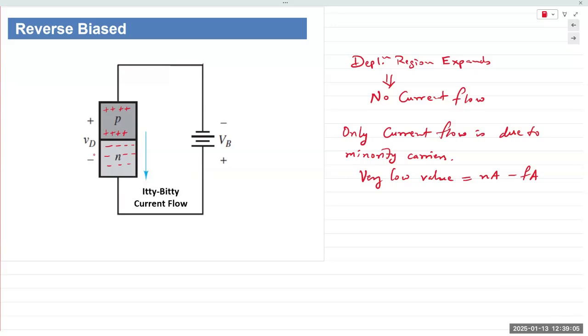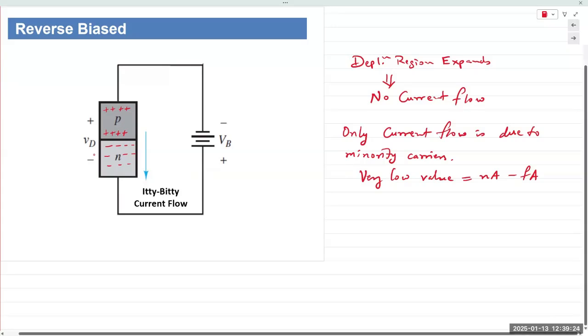And so in a P-type material, there is an excess of positive or hole charges. Those are the majority carriers. But there are still intrinsic electrons that are present, and those are low in number compared to the externally introduced dopants. Hence, those are known as minority carriers.